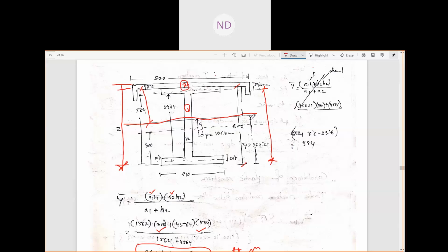This 364.21, if you subtract from this 364, which is the CG, okay, let me do one thing. AR square we are finding, that means here it is mentioned like AH1 square. So if I show you here, H1 square was the distance between the CG of this entire built up member and the CG of the I section, the first one, because it is H1 here.